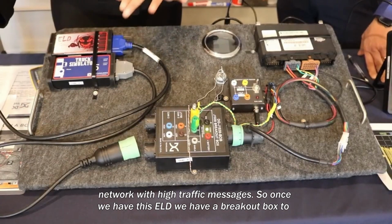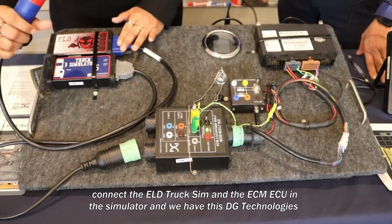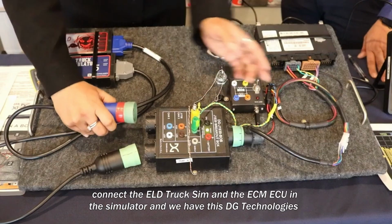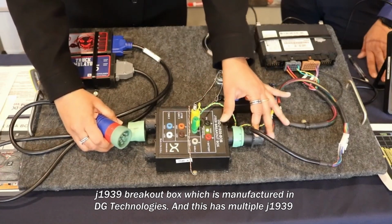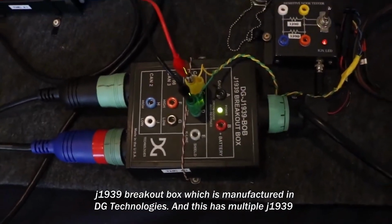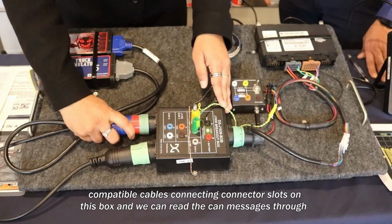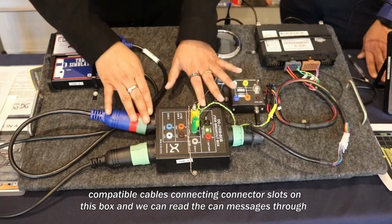Once we have this ELD, we have a breakout box to connect the ELD, truck sim, and the ECU in the simulator. This is a DG Technologies J1939 Breakout Box, manufactured at DG Technologies. It has multiple J1939-compatible cable connector slots, and we can read the CAN messages through the box.